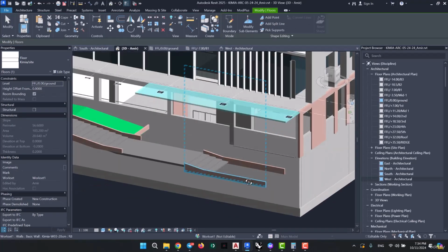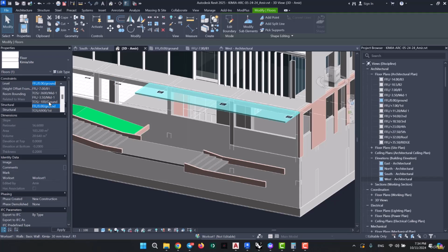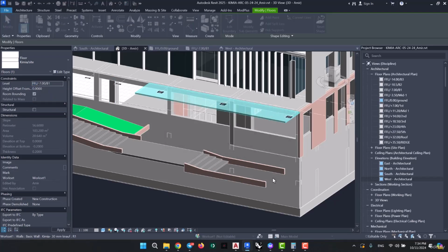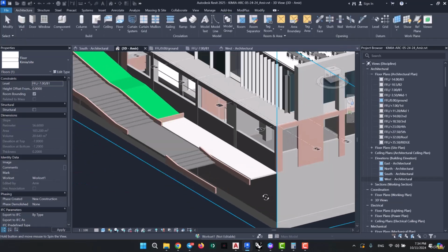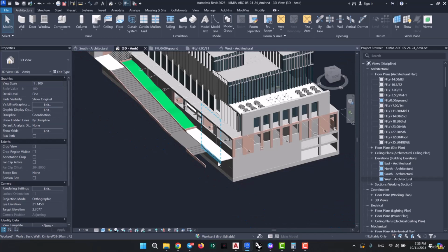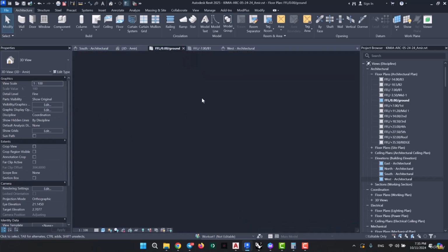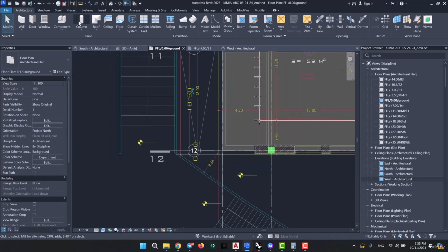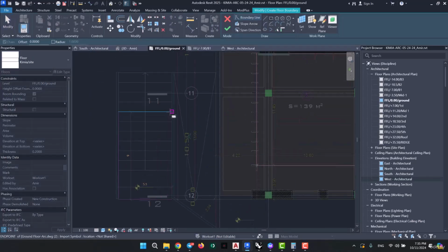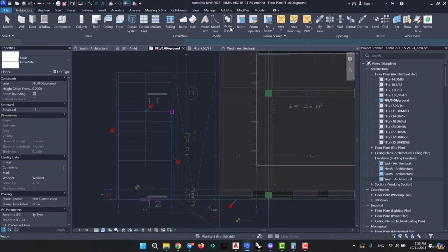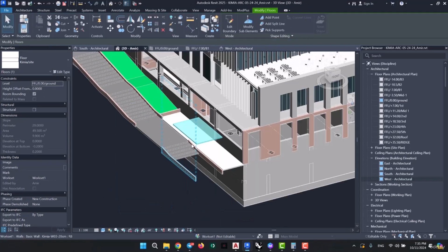Alright, so this one also needs some offset readjustment. So for its level, I'm going to set that to the first basement's offset. And it's going to come down like so. And thus, this is how we can model all the elements that we need for our site and finish that area. But besides that, I'm going to also draw one more piece of floor for the bottom of the stairs. We're going to draw this one more floor to fill this empty space and basically complete our site.